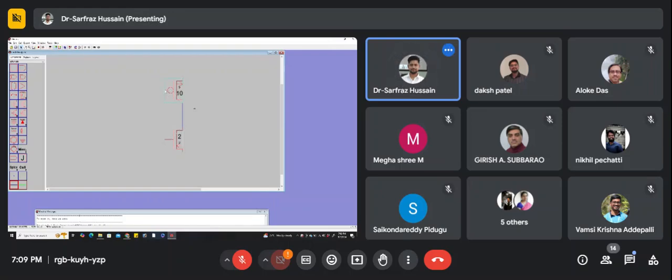Okay, so again, what I'll do, I'll place this cursor near to the gate of the PMOS. I'll left click, then right click, drag it. Okay, so you can drag this one. Okay? So you release it, so it will be like this. Then again, you drag it with the right click and release it. Now for the NMOS, again, you select the NMOS. Now at this particular point, you can right click and drag, and then release it. So this way you can actually make the connection.